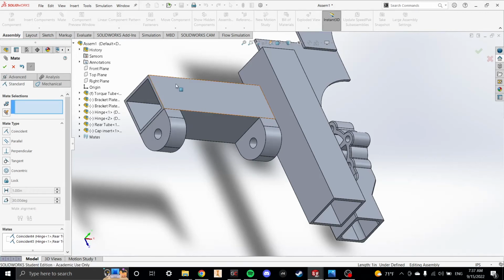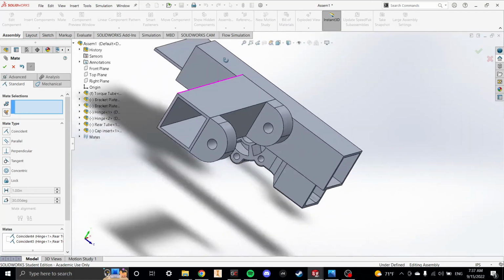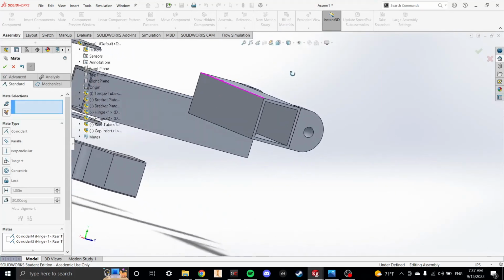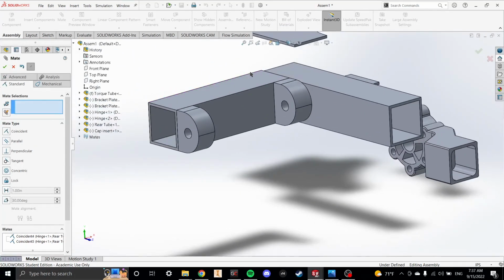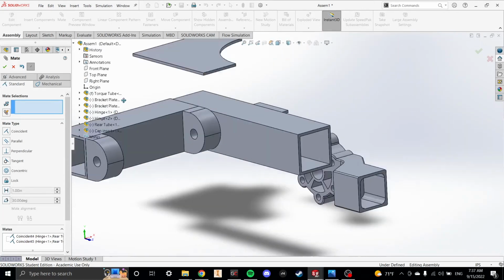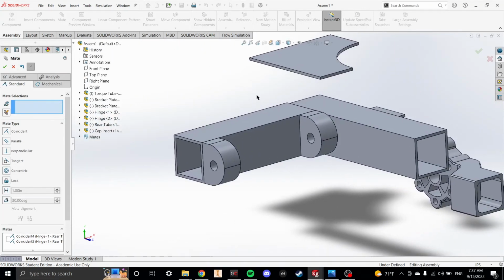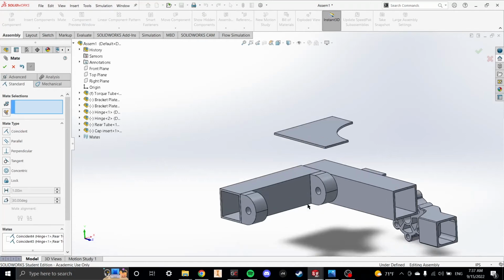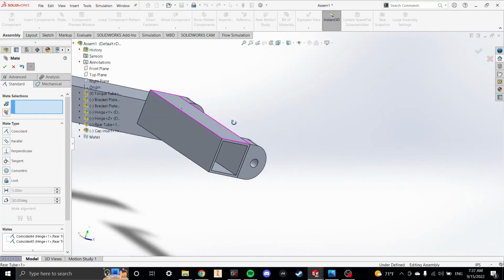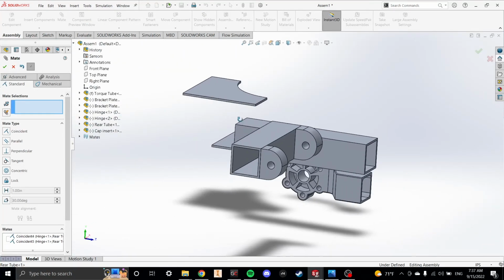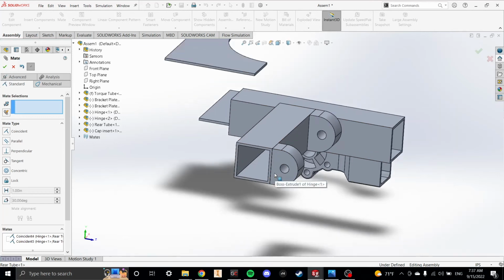And something I wanted to note really quickly, because I just remembered this, movement as I move around. If you press the middle mouse button, it allows you to rotate. If you press Control middle mouse button, you can drag and pan. And if you want to zoom in and out, it's just the scroll wheel. And so that's how I'm navigating around these objects and getting the right angle on these constraints.